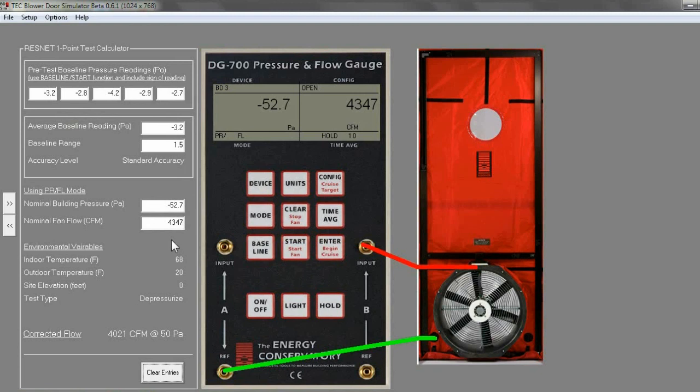And now it'll do an adjusted CFM calculation. So we're at 4021 CFM at 50 is what our actual reading is. So we're much closer to our actual 4,000 CFM reading. And if you do this with a slight wind, the simulator isn't perfect on how it simulates wind, but it does give you a sense of what is actually happening, and giving you some realistic numbers that you can visually see. Usually when you run this test, you'll be within probably 30 CFM of CFM at 50. I've run it where it's been within 1 CFM when using a slight wind.